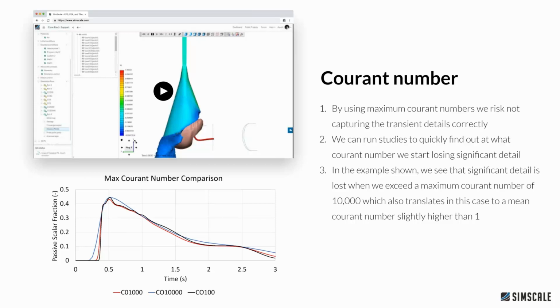But what we'll probably find is there is no significant difference between, say, a Courant number of 100 and a Courant number of 10. So we could maybe go for 100, or in this case, I would choose 1,000. And if you're familiar with mesh independence studies, this is very much similar to that kind of study. So we're looking at what is the most cost-effective scenario in our case. What are we interested in? Can we get the key results from this Courant number? If yes, then absolutely go for that Courant number.